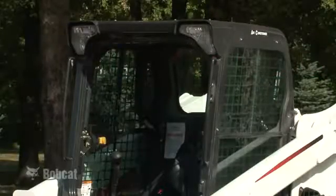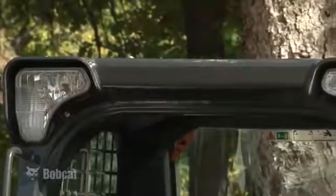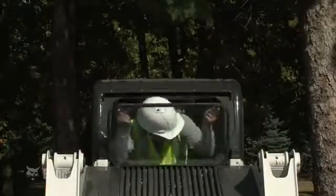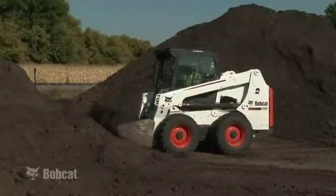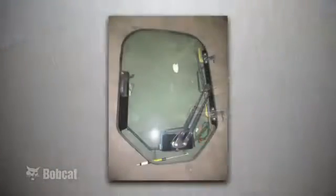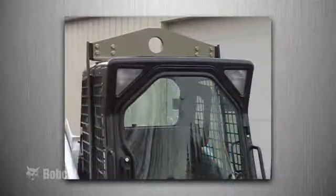Bobcat loaders are equipped with many safety features. The cab is the most obvious. The structure provides falling object protection, or FOPS, and rollover protection, or ROPS. The FOPS and ROPS should never be removed or modified. All cabs have a rear opening for a secondary exit. Your particular job application could require additional accessories or equipment, such as a special applications kit to restrict materials from entering the cab, single-point lifts, or a fire extinguisher.